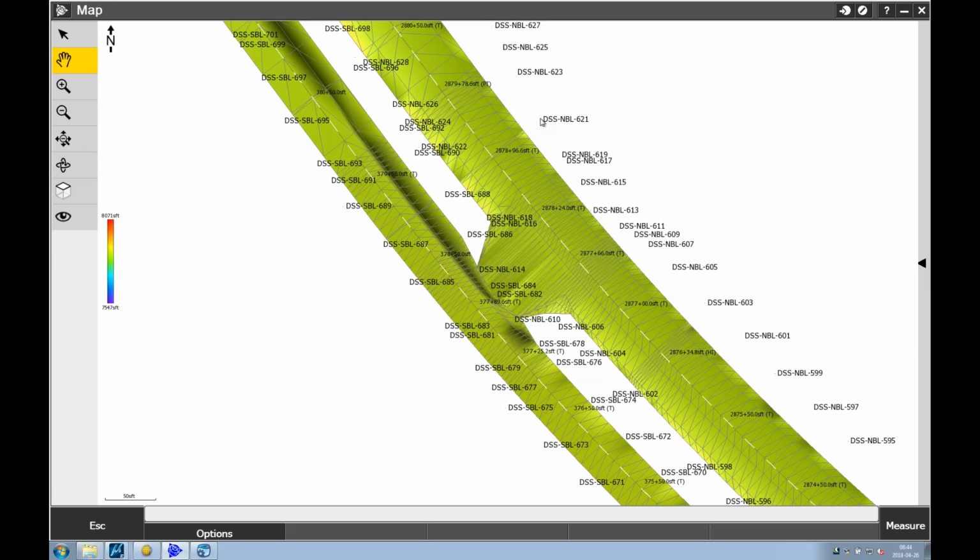This is useful to us, even though we've got the side slopes in our road model. Sometimes we do things like daylight cuts or daylight fills where there's more than one area out on the ground that we could potentially catch our road model, and we want to make sure we get out to the right spot. So we'll use these as a starting point when we go out and stake from, and then adjust as necessary from there.